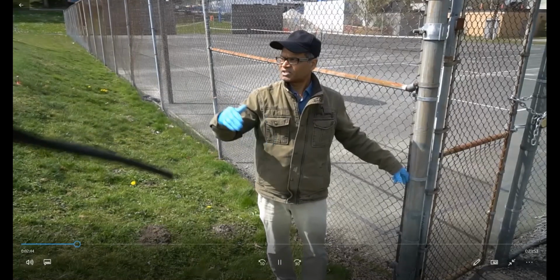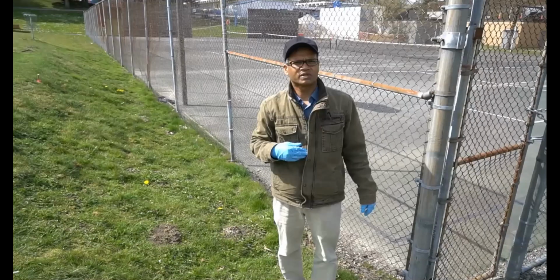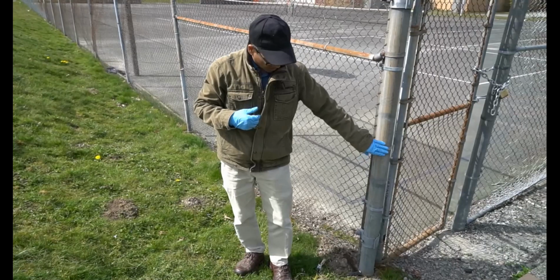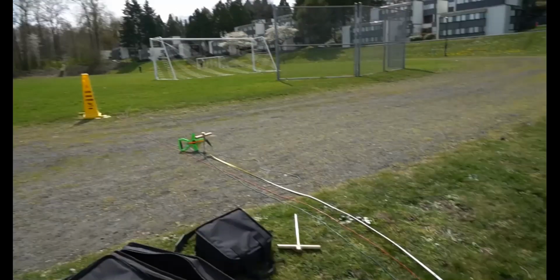So in the setup, the distance from the grounding reference point to our probe is 50 meters, we are assuming, and this is our grounding reference point. From here we'll use another probe, and move it each 5 meters and measure the voltage.